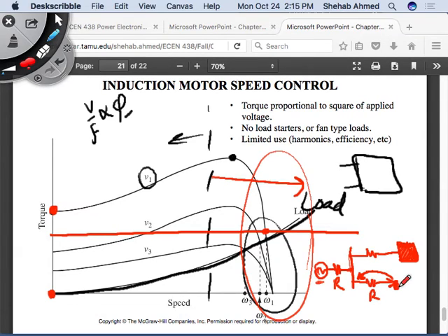But what if there's a big voltage drop, huge current? If there's a huge current, then there will be a voltage drop here, another voltage drop here. So the voltage at this node is equal to the voltage at this node plus this drop plus this drop, right? Which means the voltage here, which this other person was taking from, this person is using the same voltage that you have, this voltage has now changed. It is no longer close to your supply voltage anymore. It's lower because of what you did, right?